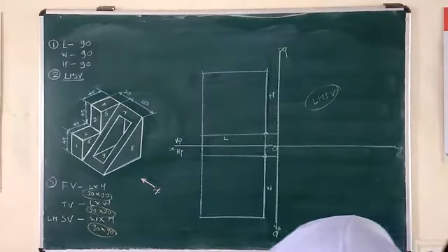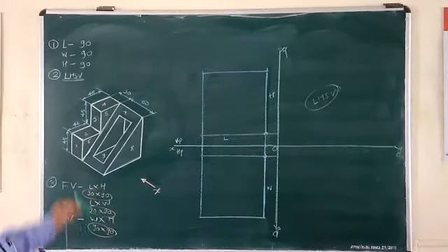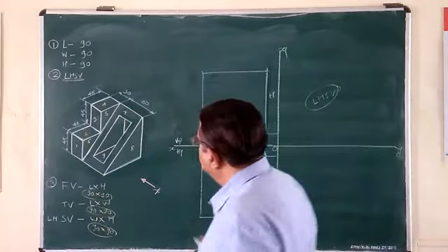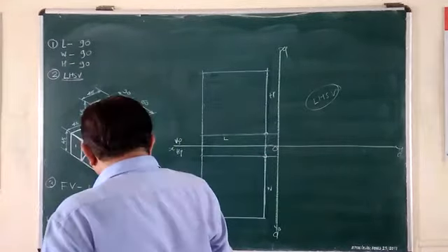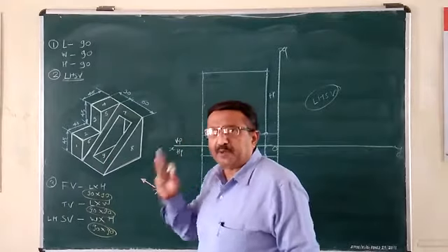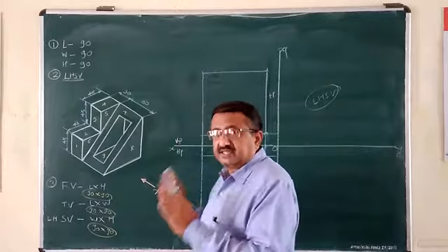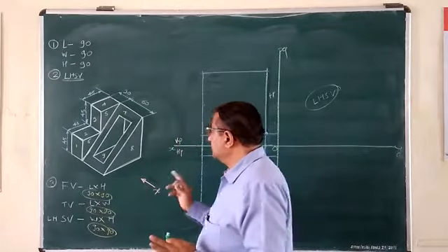Now, the very next step is to start observing this figure. Just concentrate on this 3D object. Now you have to observe in the direction of X, so that only two parameters for the front view, length and height, are required and essential, and width should be absent.